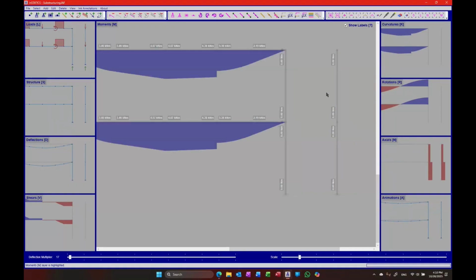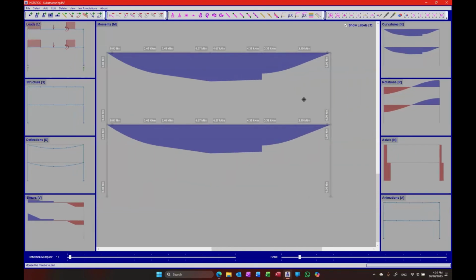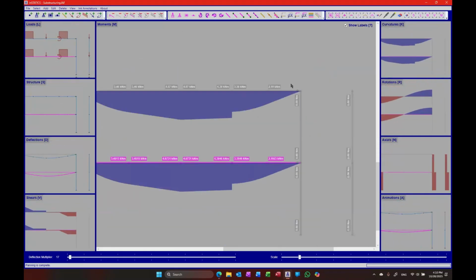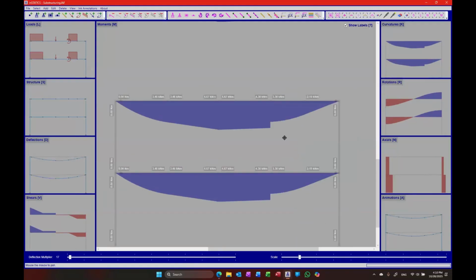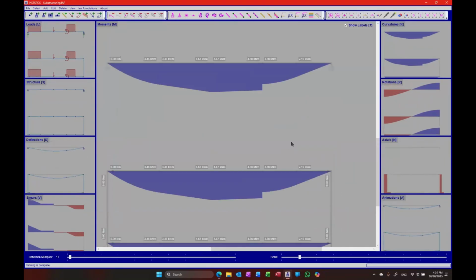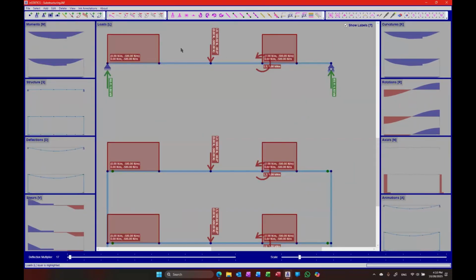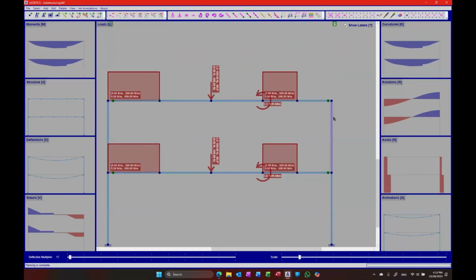So if the structure allows it, you can do substructuring, solve the easier to solve parts of it separately, like this column being solved separately, right? As in this case. But I have to find the load path and understand the load path, right? So 1.1 kilonewton here. After solving this, I understand that it's not going to affect my column.